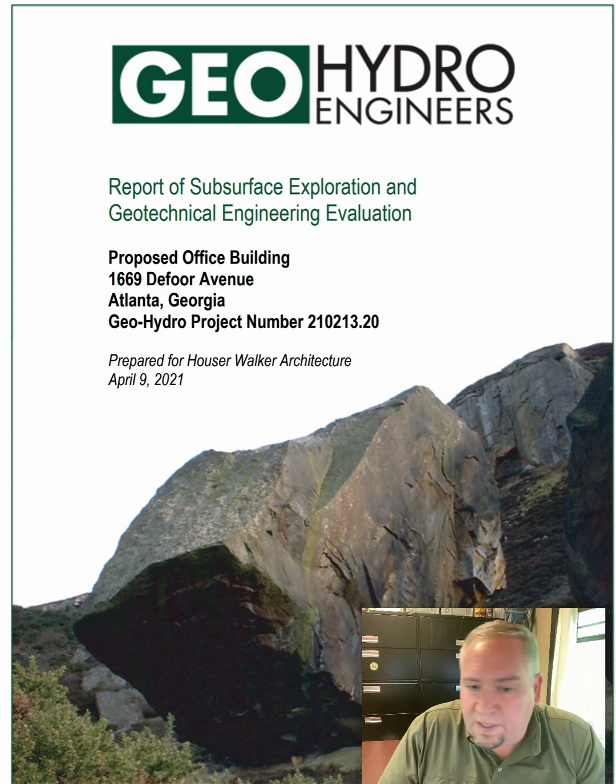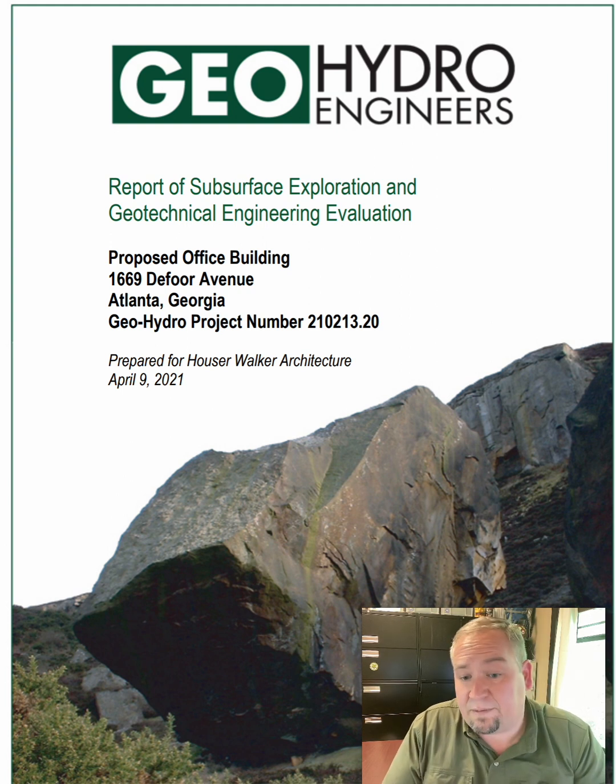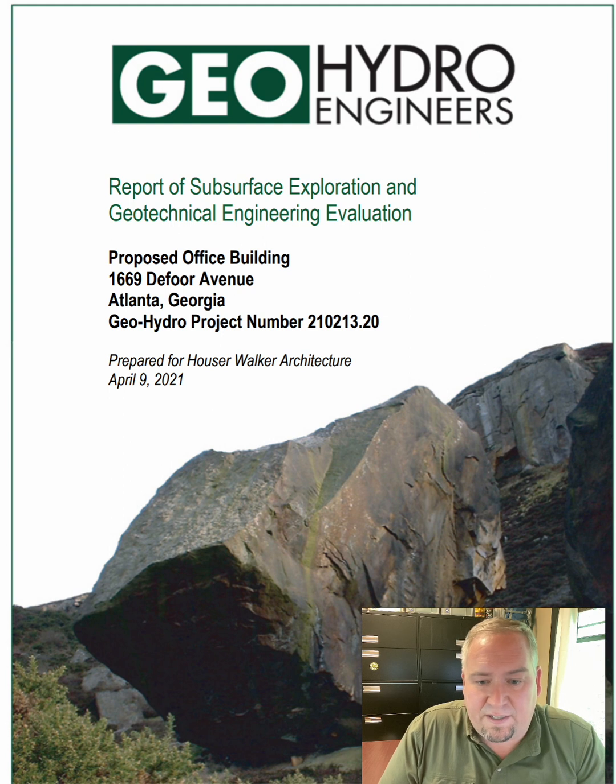Some of the other little nuances to a geotechnical report is to have agreements between, say, the contractor and the general contractor or owner, and agreements as far as terminology. What do we call rock? What do we call rip rock or partially weathered rock, PWR, or certain types of stone, because that can indicate densities in the rock so that we can know if we're going to have blasting or we're going to use a rock hammer or we can rip it out.